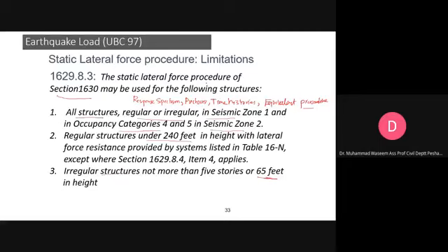Now we will discuss the earthquake design procedure. Okay. Now there are different procedures which are mentioned in the codes. We can use them to evaluate the seismic response of your building. They are known as response spectrum analysis, pushover analysis, time history analysis, and the simplest procedure we call the equivalent static procedure or static lateral force procedure. Okay. Obviously, you know that in your building you should not have those plan irregularities and vertical irregularities.